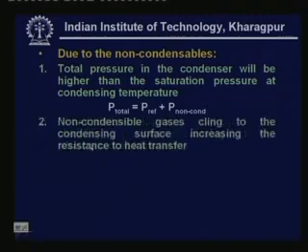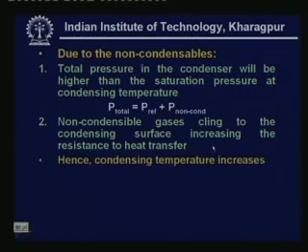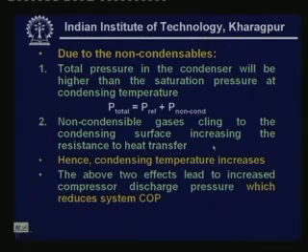Not only this, you also have a second effect: the non-condensable gases cling to the condensing surface, increasing the resistance to heat transfer. Hence the condensing temperature increases. So because of these two factors, there is an increased compressor discharge pressure. Whenever there are non-condensable gases, the condensing temperature increases and the discharge pressure also increases. Once the discharge pressure increases, the compressor power input has to increase for the same mass flow rate. So ultimately the COP of the system reduces.